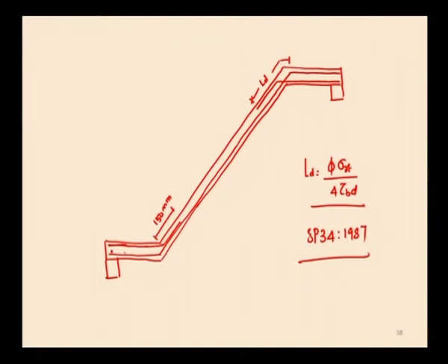Then, in order to keep this main reinforcement at the proper spacing, the distribution reinforcement has to be provided. This is 8 mm at 175 mm center to center.